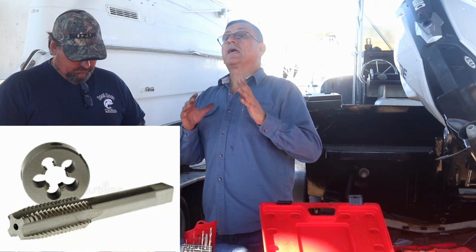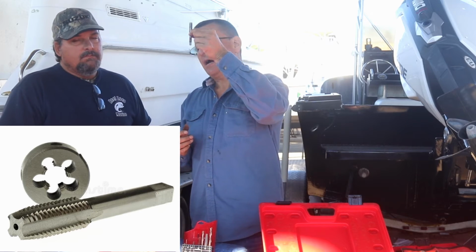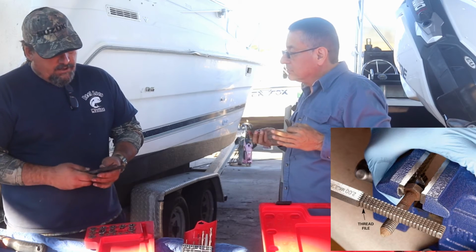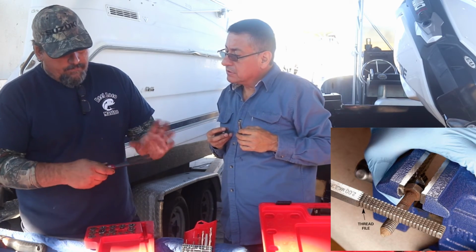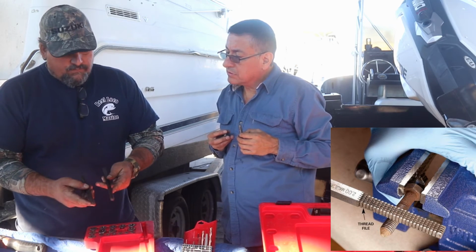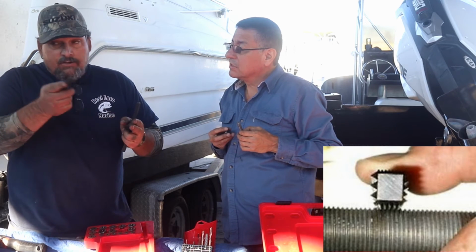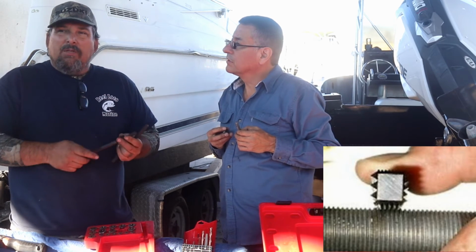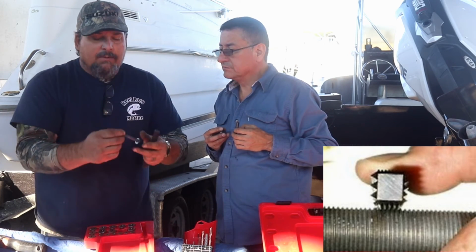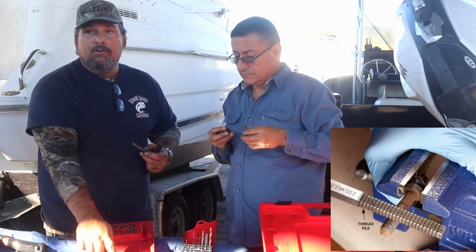We are going to repair threads in the shop. How? We are going to pass the tap again, or pass the die again, or they also sell these tools that have threads on them. Different threads, depending on the application. So obviously there's coarse, fine, metric, and standard. What you do is you put the bolt in a vice grip, and the vice grip in a vice, and you can work the thread. This is only specifically for if you damage the beginning threads. It's really not to fix the whole entire thing. If you're going to fix the whole entire thing, you would use these.